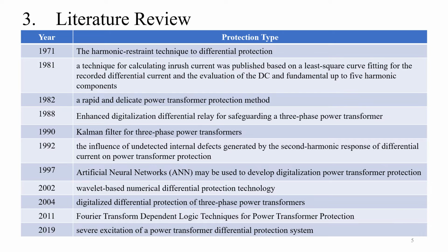By analyzing the signal of this criteria function for three phases, the internal disturbance may be precisely distinguished from the inrush current situation. The primary advantage of the procedure is that this is accomplished within around half a cycle following the disruption event.